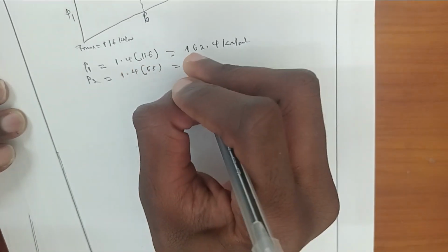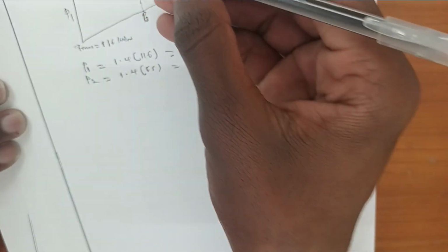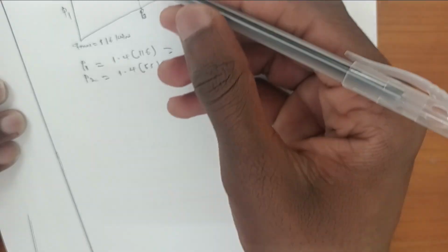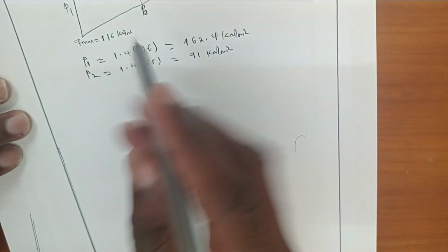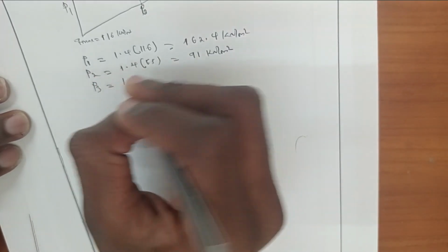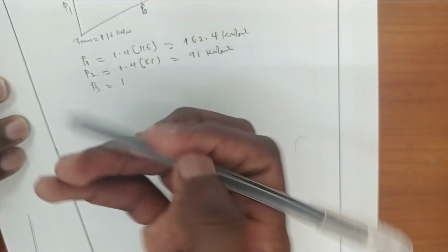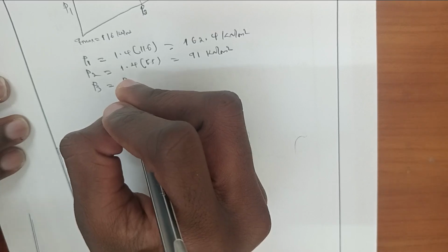It will be equal to 91 kilonewton per meter square. Now let's determine the pressure at the fixed point, at the point where the heel slab is fixed at the stem. This is pressure 3, which is obtained because the soil pressure increases from the minimum pressure up to the maximum pressure. So to obtain the pressure at this point,